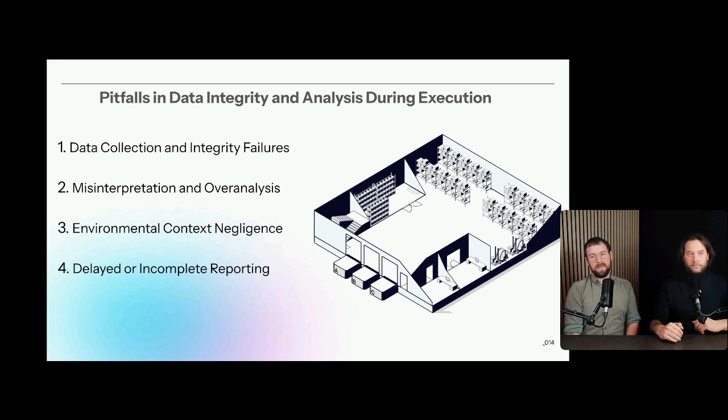Absolutely. And I think this ties really well into a question we got here from Tolcha. Sorry if I'm mispronouncing your name. Does the position of data loggers arranged in a storage room affect our data? This goes back to the risk-based approach: it has a large impact where exactly you place the data loggers for what kind of data. Normally we have a saying that a sensor only really measures itself. A temperature sensor measures the temperature of itself. We just hope, and we account for, how well that correlates to the temperature of the product that we're actually trying to map.